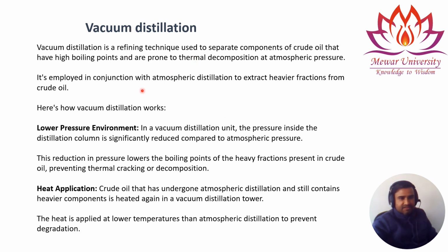So, as you can see in this slide, we have written here that vacuum distillation is a refining technique used to separate components of the crude oil that have a very high boiling point and are prone to thermal decomposition at atmospheric pressure. So they may undergo thermal decomposition at higher temperature. They may be converted into some other product at atmospheric pressure. So here in vacuum distillation, basically we are lowering down the pressure.